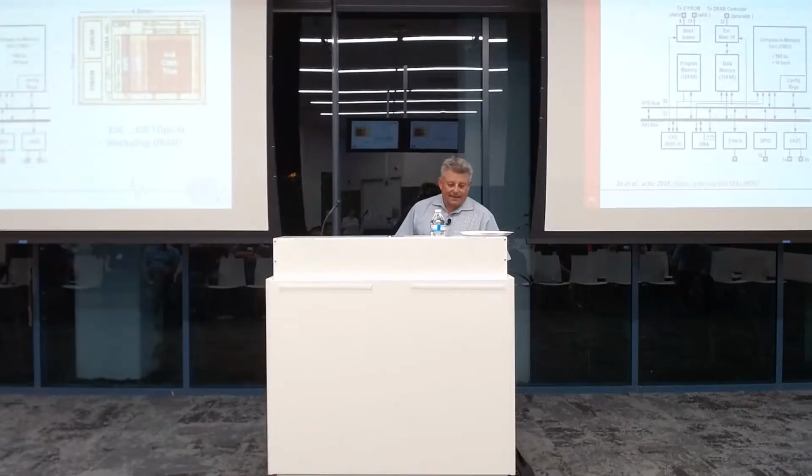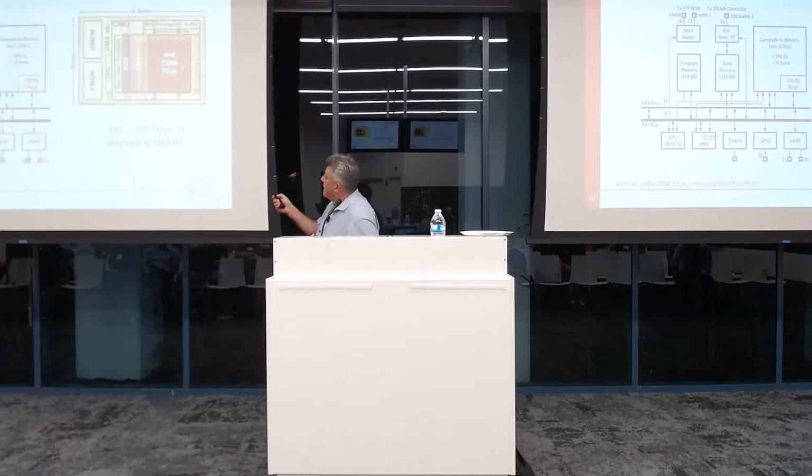They not only did that, they also put together something that is almost a complete processor. They put 16, 4 by 4 of these compute memory tiles on the chip with ADCs on the column. This is a batch normalization circuit that you need for any neural network implementation. And they have some memory access control and so on. So here you see a little bit about the architecture. One of the downsides of this processor is it doesn't have a whole lot of memory on chip, so it relies on the external DRAM.